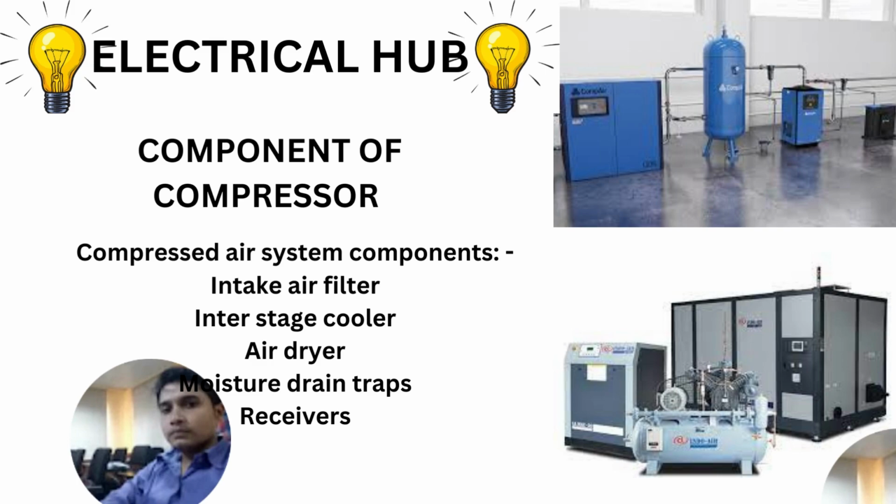Here, at every stage the air is cooled to increase the efficiency of the compressor. Number three is the after cooler. Interstage coolers are provided to cool the air, and the after cooler is the same, so that there will be a minimum loss due to the heat.